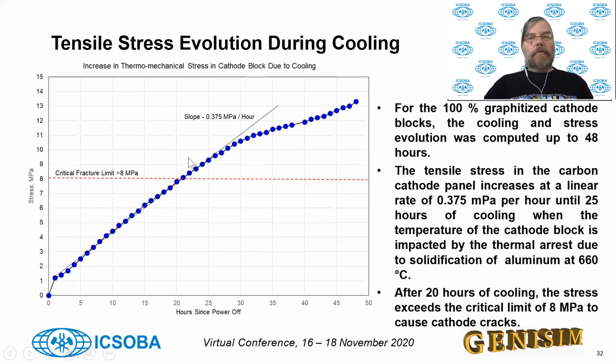Of course, this model is not forming cracks. Even if the property of this cathode is quasi-brittle, we are modeling elastic only. So we are not forming cracks, so the stress continues to increase. So it's not so relevant what's happening above 8 megapascal anymore.